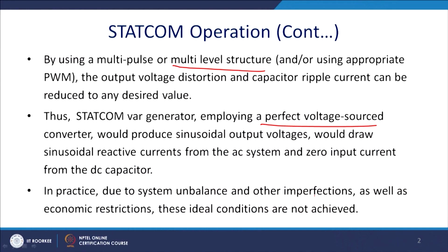In practice, due to unbalance and imperfection, maybe the value of the inductor is a little different. For this reason there might be imbalance, and even a source unbalance. We actually tolerate some amount of source unbalance because of economic restrictions, so this ideal condition is not achieved. So, there is a real power exchange between this Statcom and the power system.